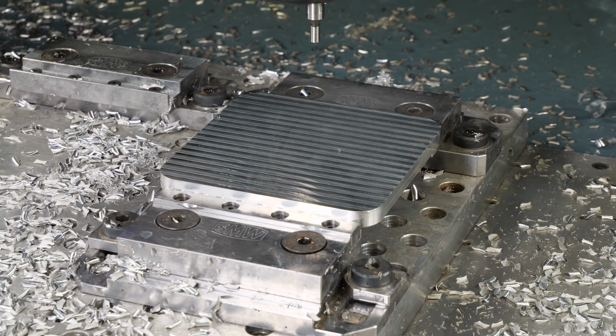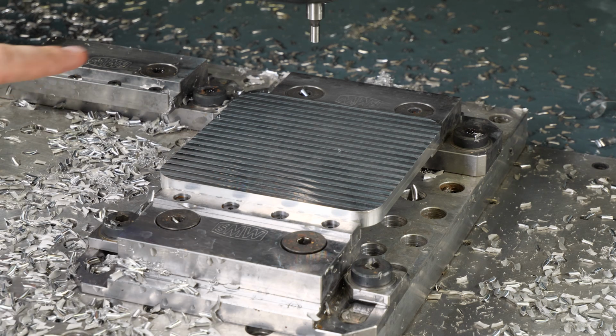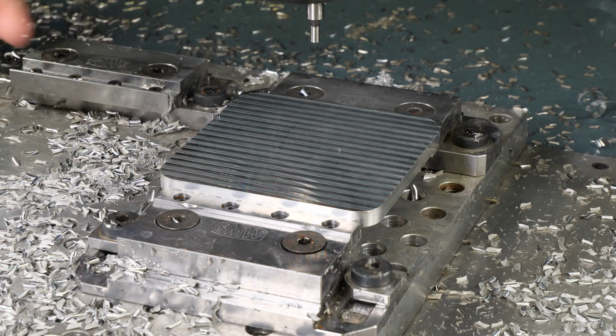Now if you look up, I've already got one loaded into the spindle here. There's our edge finder. What an edge finder is, is basically a blunt tool that has a slight wobble at the head. As you start to spin around, that head of this edge finder is about 200 thou, and it comes down to your part, and you start to touch the part with this edge finder, and this wobble will become less and less and less, until finally, once you get at the edge, a little past, it'll shift to the side very quickly.